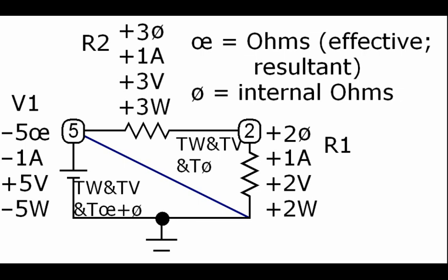So this theme of current saturation is a very important theme, because if voltages should ever rise excessively, what happens? It arcs to the nearest grounding point, some point that has a significant voltage less than what's building up, and the air ionizes sufficiently to cause a pre-arcing channel of ionization which precedes the arc.